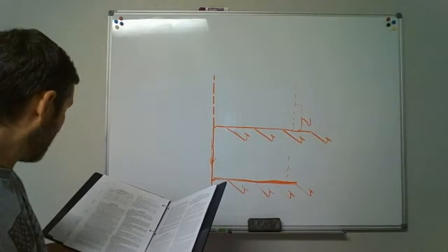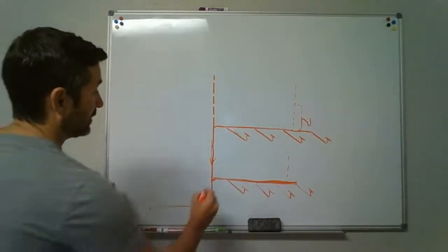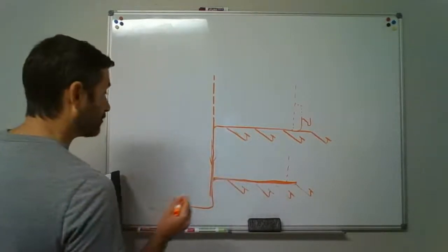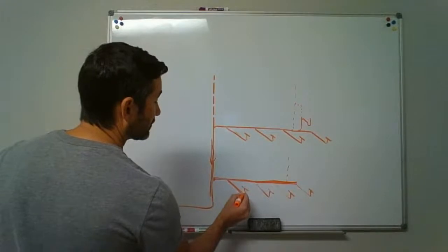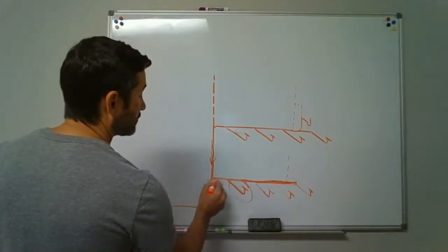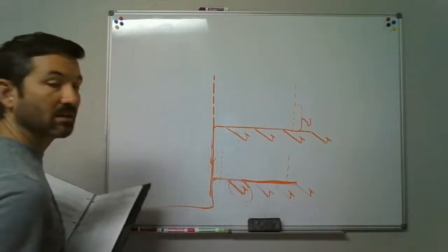Let's see, where in that horizontal branch drain? Oh, between the stack. Here's the stack, between the stack and the most downstream fixture drain. So here's the most downstream fixture and the stack. Somewhere in this is where we're going to tie up, and it's going to come up and call it a relief vent.